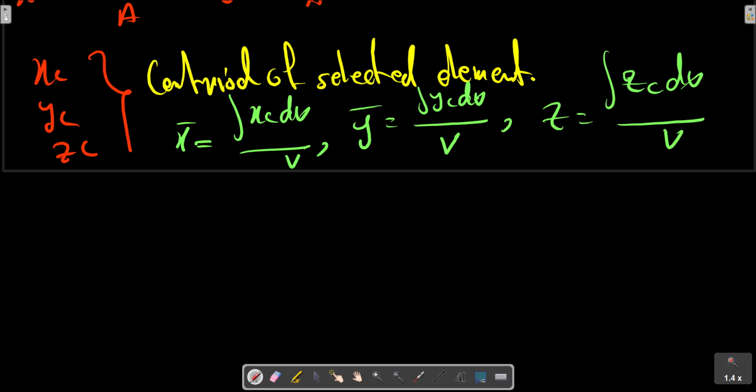Keeping in mind the physical picture of the principle of moments, we will recognize that all these equations, which are geometric relations, also describe homogeneous physical bodies because the density rho cancels. If the density of the body is not constant but varies throughout the body as some function of the coordinates, then it will not cancel from the numerator and denominator of the mass center expression.